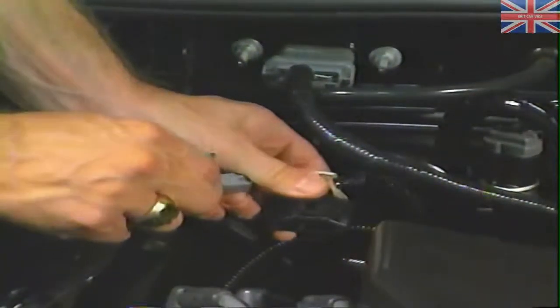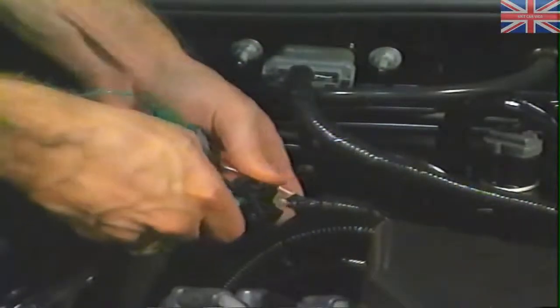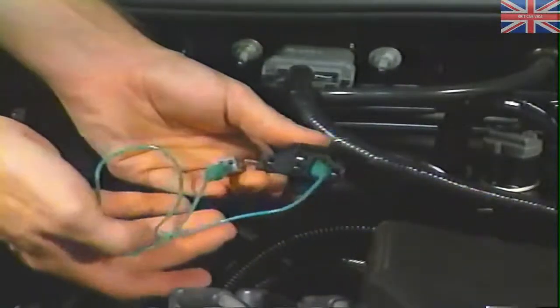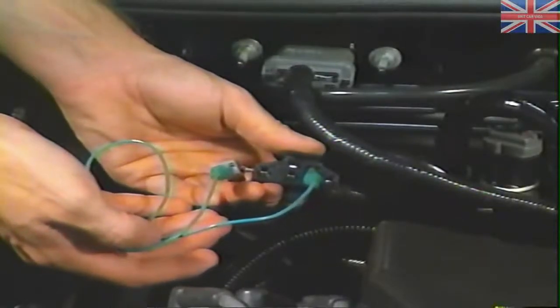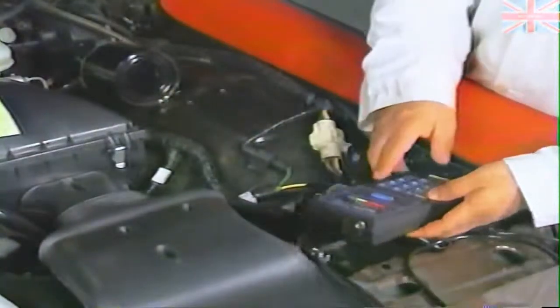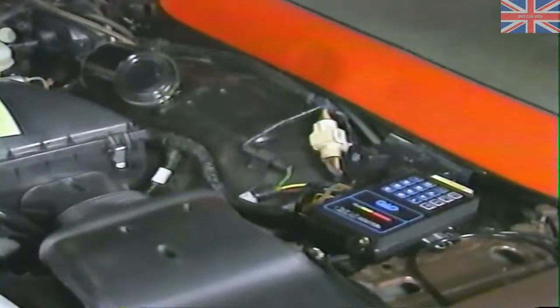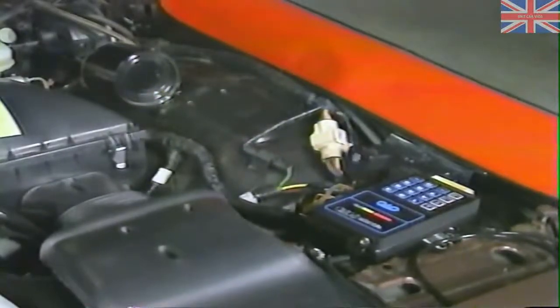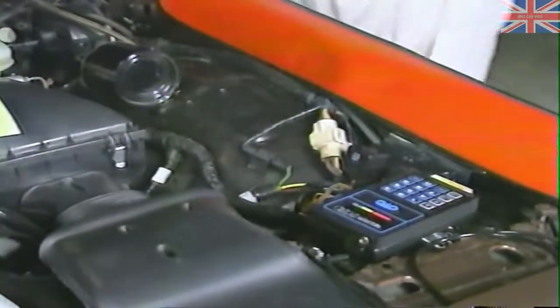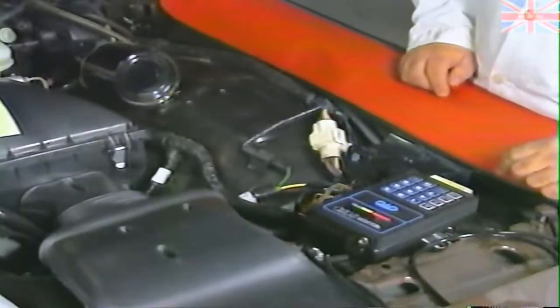It is a simple matter to utilize the check engine light. After locating the diagnostic self-test connector in the engine compartment, connect a jumper wire between the single self-test input lead and the 6-pin self-test connector as shown. Turn on the ignition key, engine off, and record any on-demand or functional test codes that appear. The on-demand codes indicate that there is a malfunction at the time you are self-testing the EEC system. These are referred to as hard fault codes.